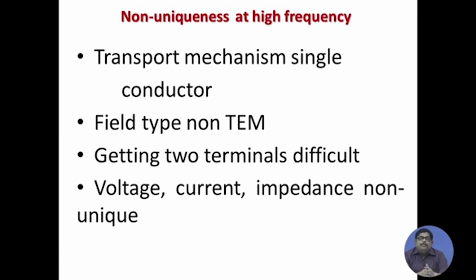But one problem at high frequency is that the transport mechanism, through which the power gets transferred, is generally in the form of waveguides, which are single conductor, not two conductor, because two conductors become lossy at higher microwave frequencies.